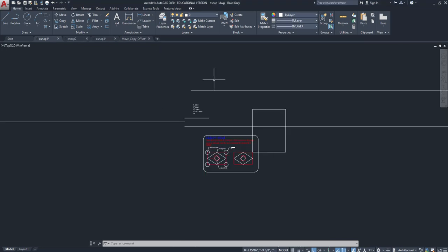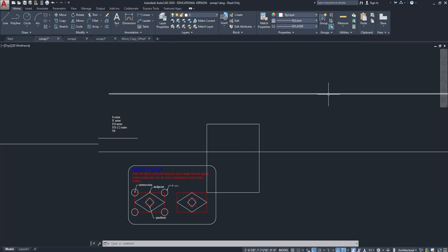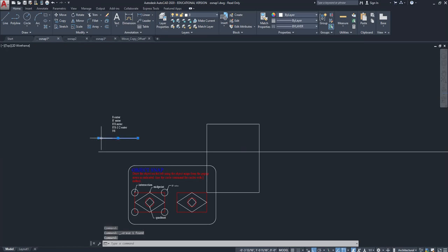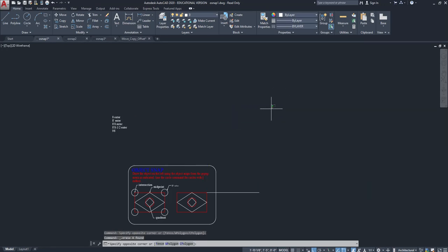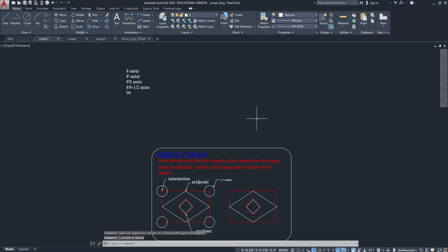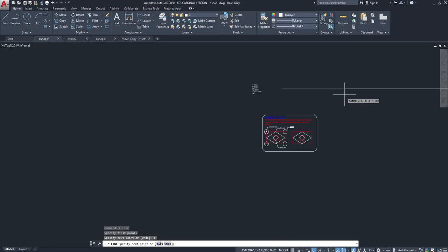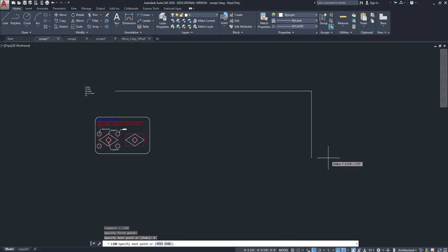So if I come over here, I'm going to delete a few of these things. To remind you about selection, I can click, hit delete, click, hit delete, click, hit delete, right? I can select all these using a selection window, delete. Okay, L for line. I click, I move in the direction I want to go. I type 4 foot. Enter, or spacebar. Spacebar's enter. Okay. Zoom out a little bit, pan over.